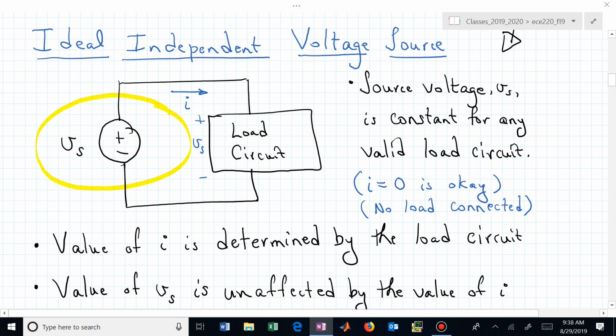One of those is that source voltage. If you say now in the lab, I want this voltage source to be 10 volts, you'll now set it at 10 volts. And if you don't have any limitations on the way that you've adjusted the knobs, that will supply 10 volts no matter what you hook up to it. That's ideal.